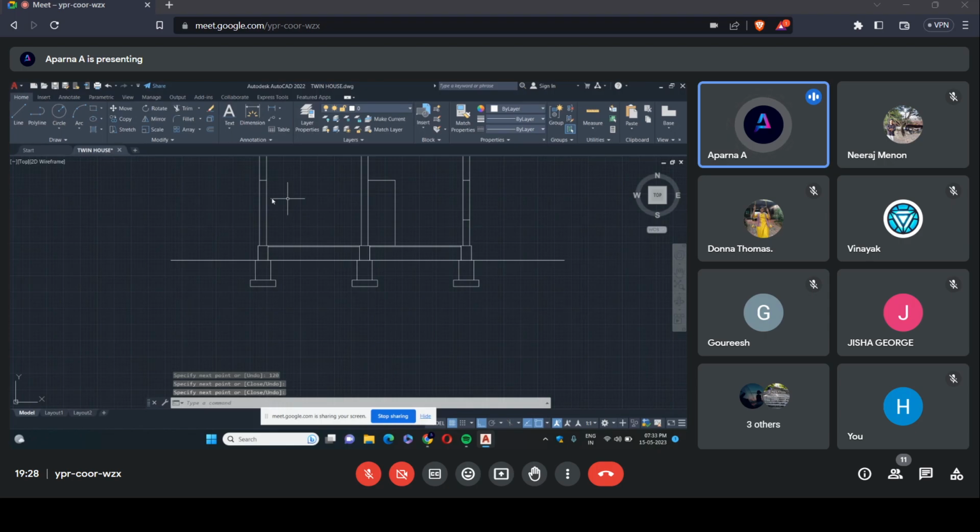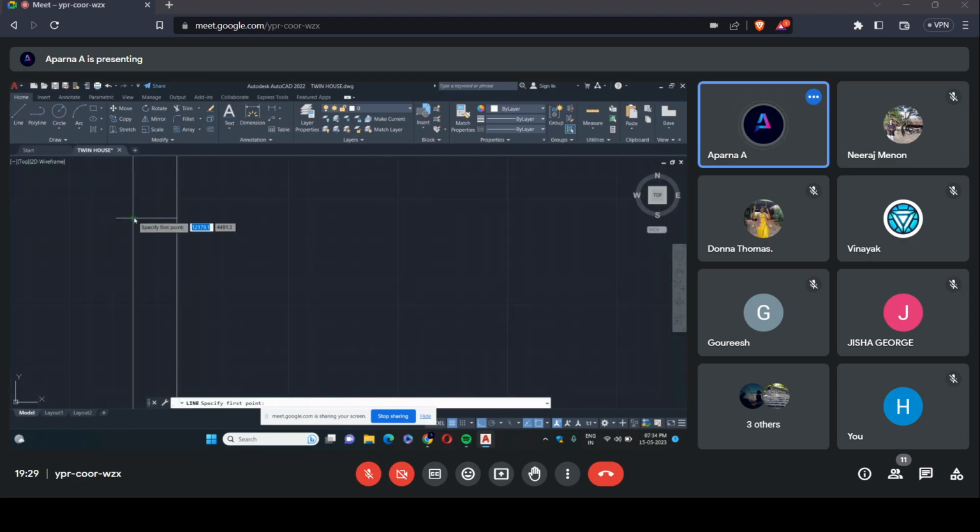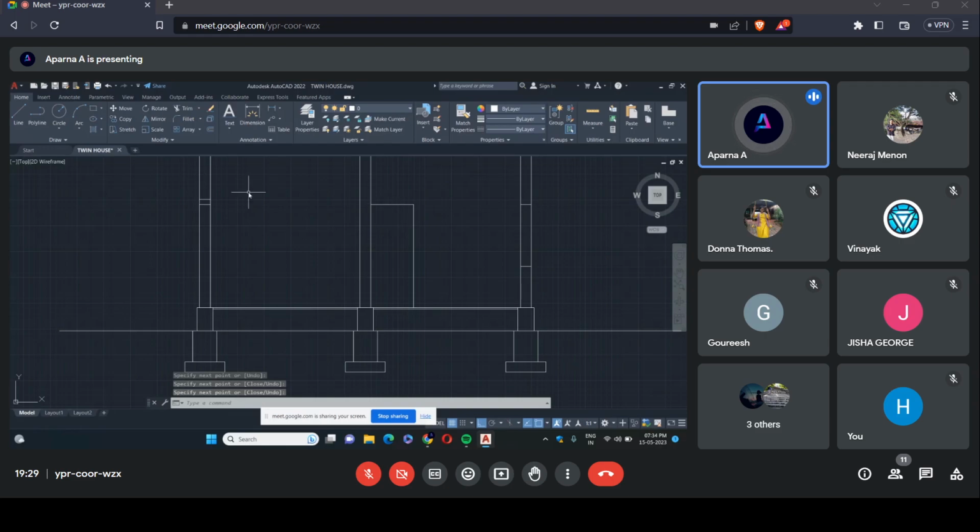now I am cutting through the window and door on the left and right walls respectively. So I need to draw a lintel which is 10 centimeter deep. For that I can use line 10. This door I am not cutting through, so there is no need to show the lintel.